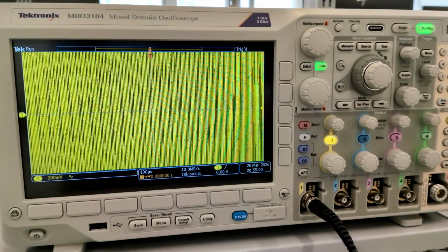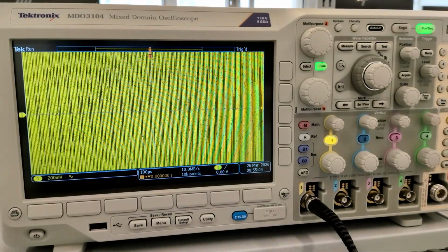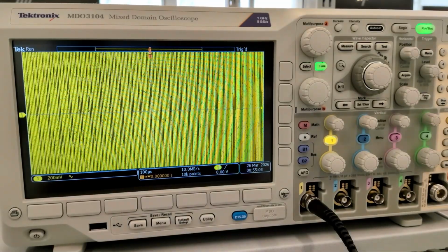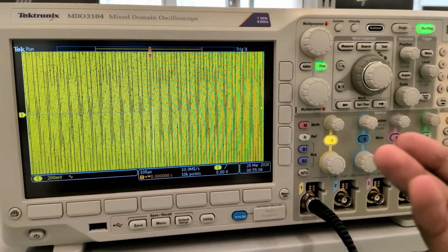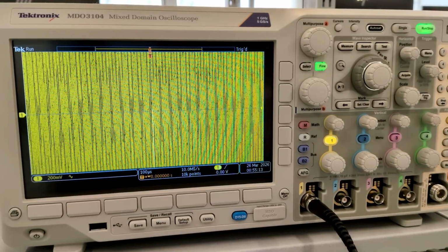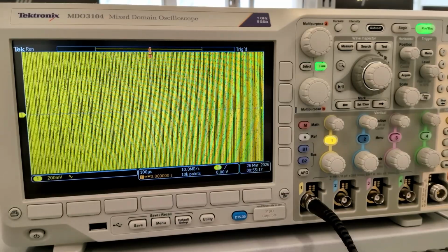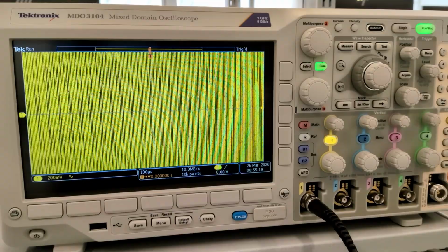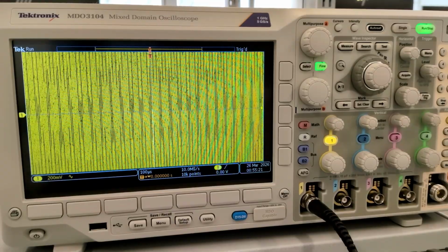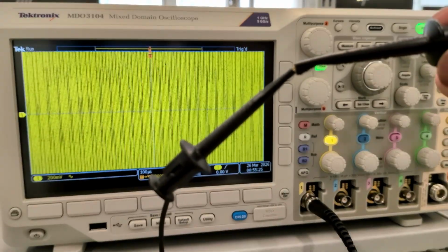And you can see how connecting the ground signal there actually cleaned up our plot a lot. The moment that I touched the 2 positive leads together, we already started to see some kind of data, but it was kind of flickering, coming in and out, which is a very good diagnostic tool. If you're trying to plot a signal from a circuit and you find that your signal is kind of flickering, the very first thing you should check is to make sure that your ground connection is good.